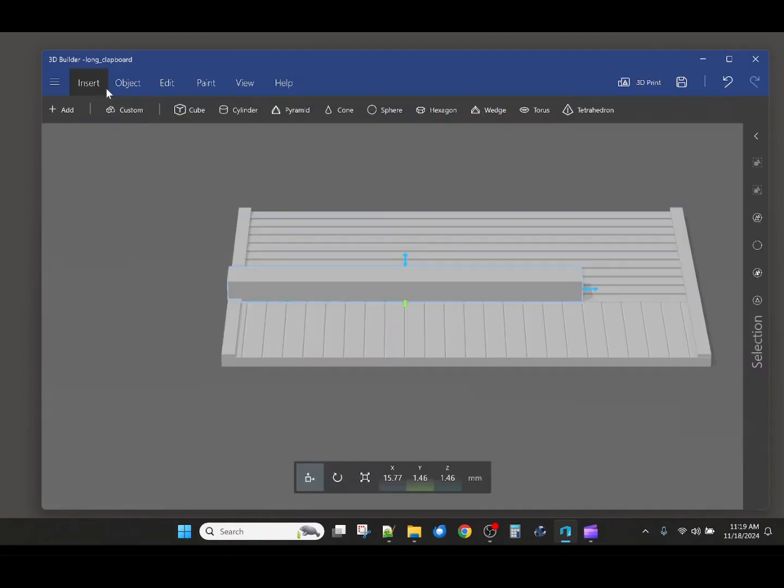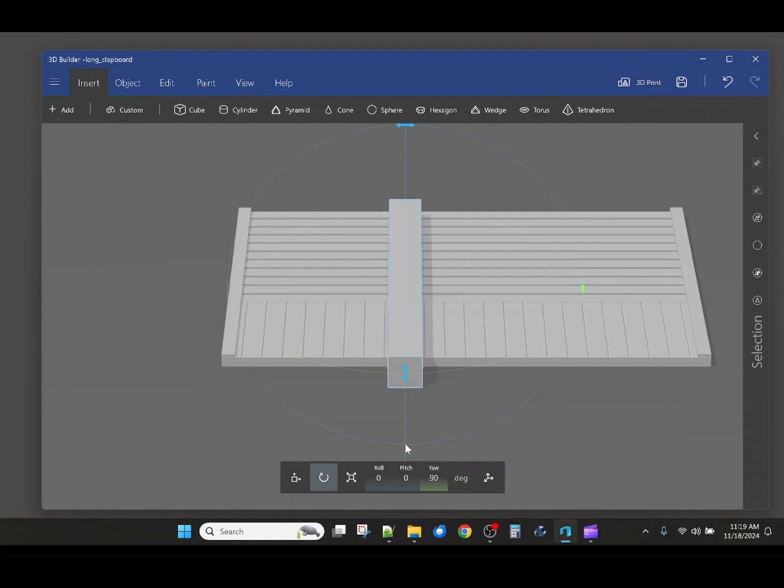First thing, it needs to be turned 90 degrees to vertical, just like the corner trim boards. Next, we need to rotate it on end 45 degrees to make the bevel edge. So we click the roll parameter, type in 45 degrees, and accept. Now, we need to move it to the wall corner in a position to subtract the bevel from the wall corner.